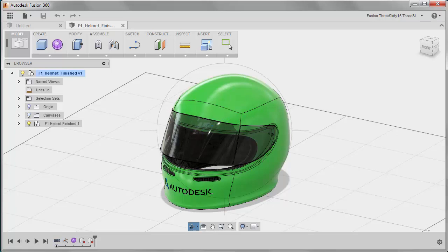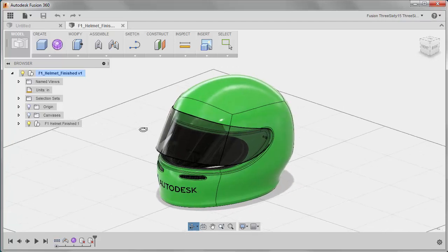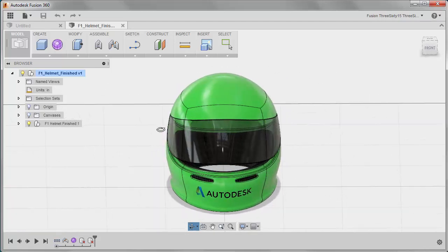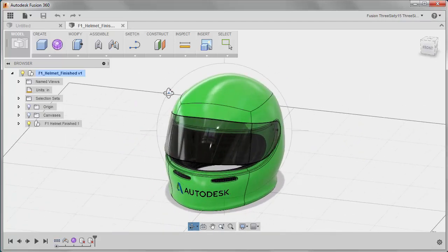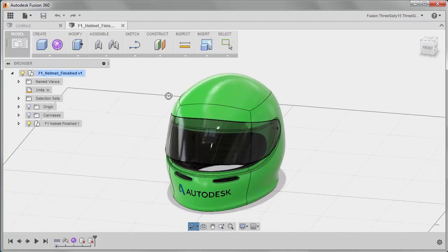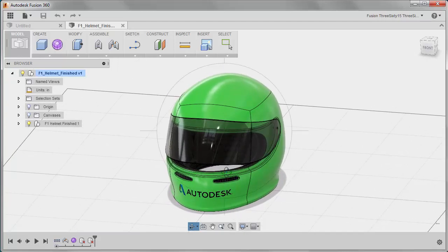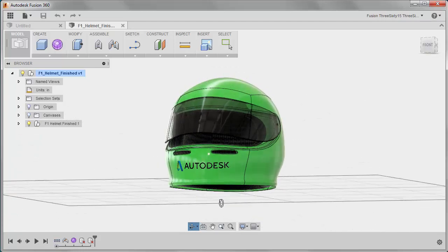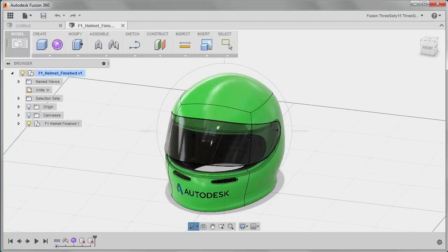With crosshairs, if I go to the outside, I'm just rotating about that angle. If I come here, I'm tilting my object, and with the bottom, we're rotating along that axis. If you hit escape, that'll turn off that orbit mode with the crosshairs.